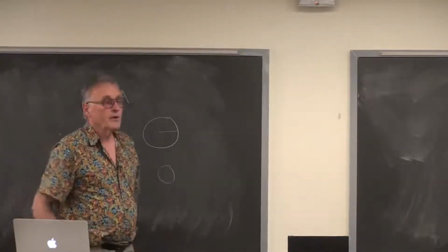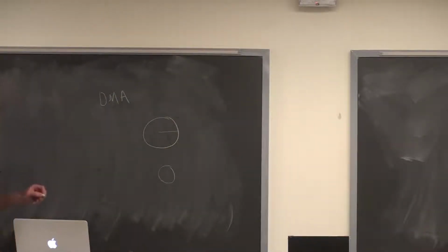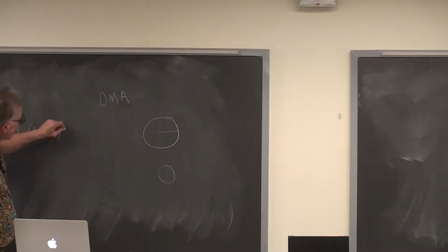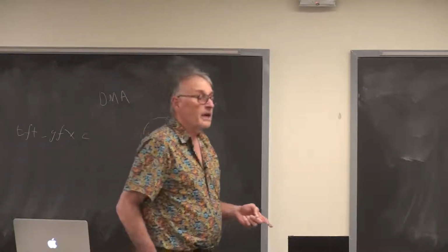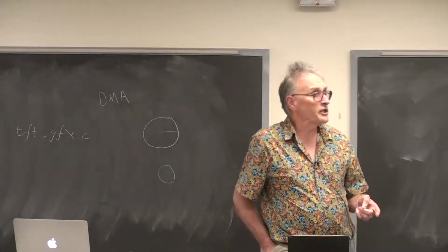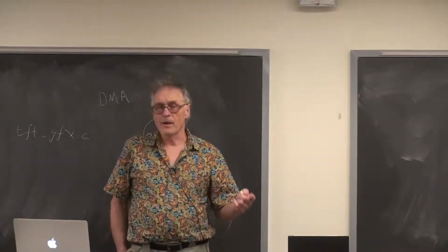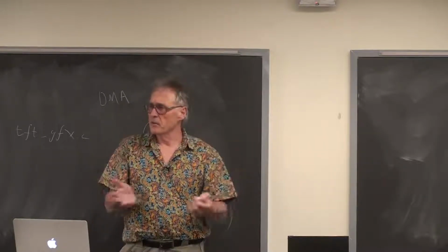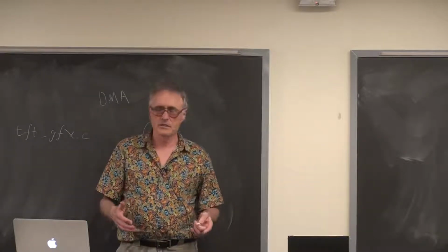Furthermore, if you go into the TFT, now this is down in the, this is how I spend my life, going into the weeds. In the TFT gfx.c file, you will find the code for drawing a circle or a filled circle. And they're using a good algorithm for that. It's called a Bresenham circle drawer. But it still requires a fair amount of calculation to figure out where the next point is, because after all, you have to do something like take the square root of x squared minus some constant squared.